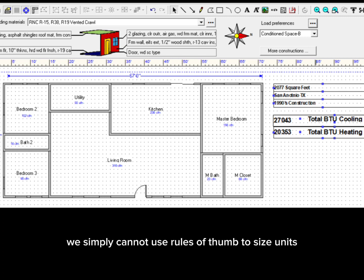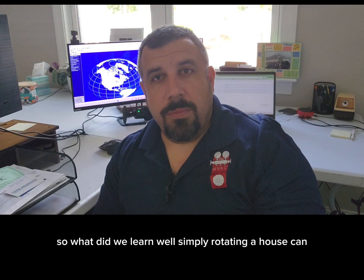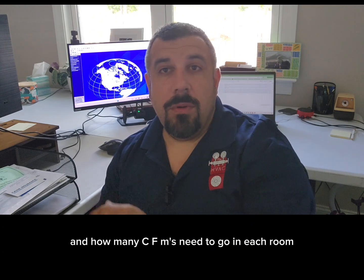We simply cannot use rules of thumb to size units, size ductwork, or even estimate how much air is going to go into a room. So what did we learn? Well, simply rotating a house could make a huge difference in how many CFMs need to go in each room.